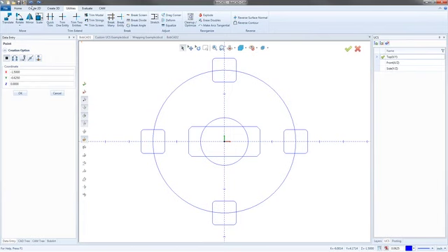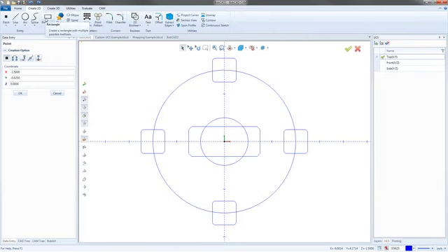I'm going to go back to the Create 2D. One thing you'll notice if you go back to version 30, I think there's 6 or 7 functions that are used when you're doing points. You've got your point snap, point coordinate, point incremental, point sketch enter, a bunch of them. So what we've done now is combine some of that stuff. Right here, if I click on this first one, it's point sketch / enter. You could think of that as a sketch function, but also a coordinates function.